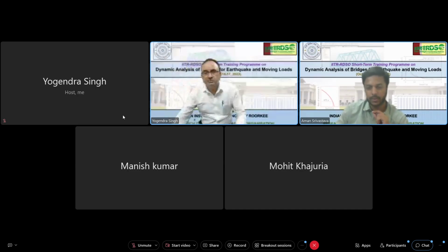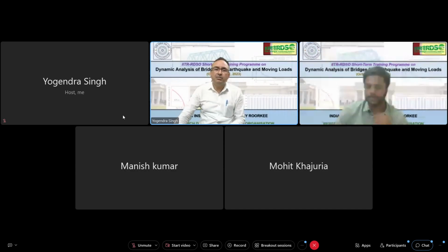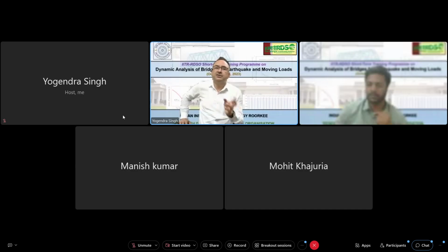Mr. Sugandha is asking a question. What is the basis of the guidelines for selection of ground motion for different type of analysis? Okay, so this is based on the minimization of the uncertainty, the variability. Suppose a bridge is to be analyzed by two people. Ideally, both should come out with the same answer. But what will happen if both people have used different sets of ground motion? Their answers are going to vary. That's the problem. So we need a standardization of the selection process so that anybody analyzing that bridge should come out with the same response. Otherwise, different people can come out with different designs. In one case, it may be safe; in another case, it may be unsafe.